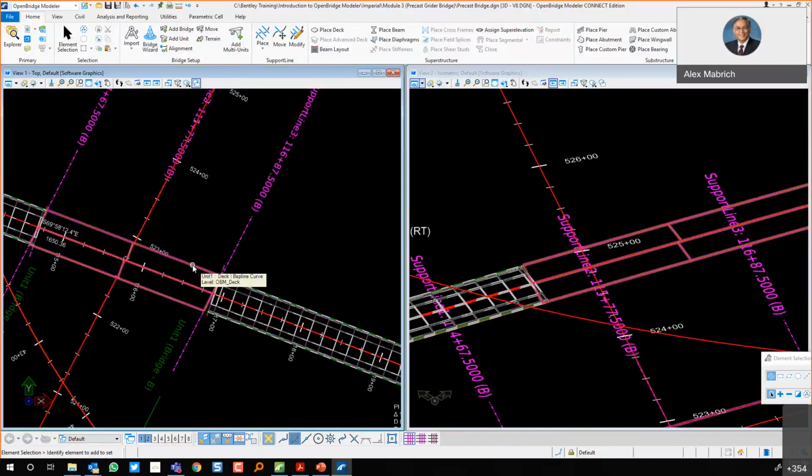Here, if you report the 1.5 as part of the deck itself and then provide deck elevations, then you have to do the full deck thickness, right? 9.5, as Devon is asking here. And then on LEAP, you can reduce that to make it a structural concrete thickness there, right? So that will be on the analysis part. So that's how you can do it, right? So that will be it.